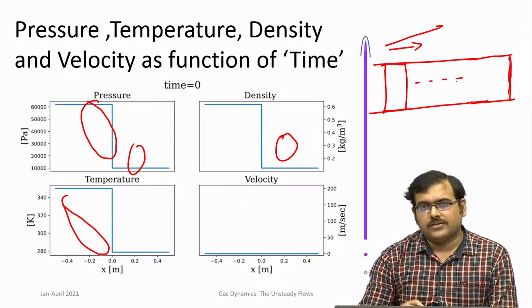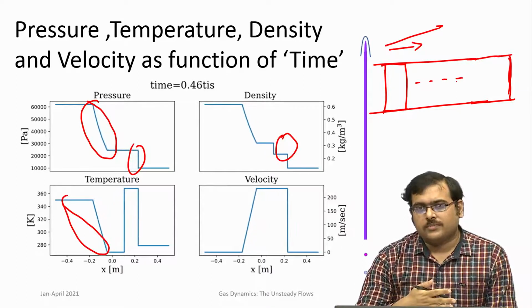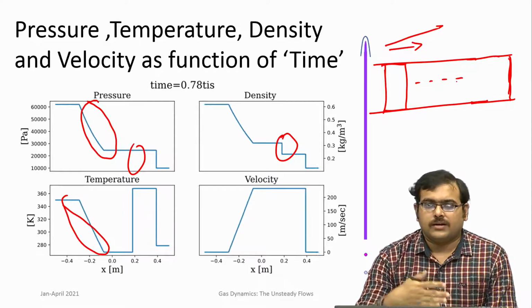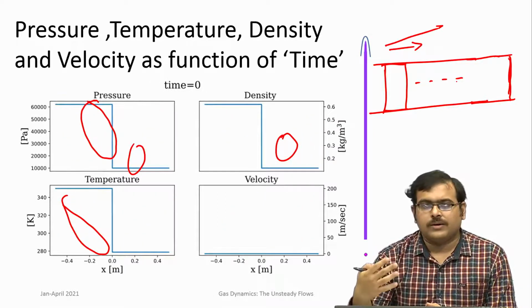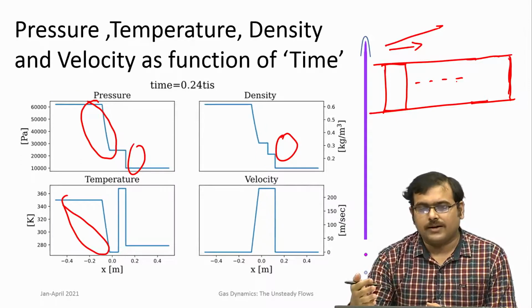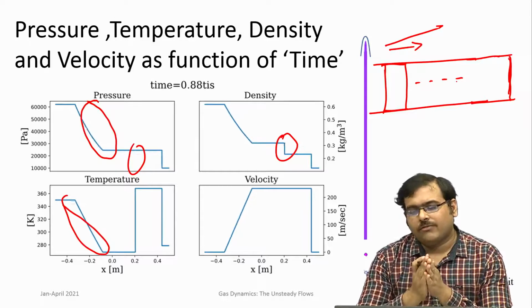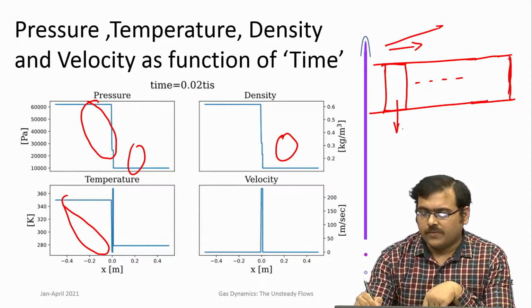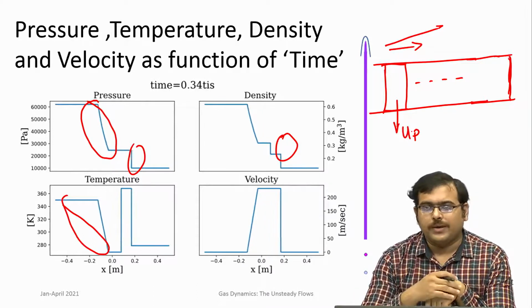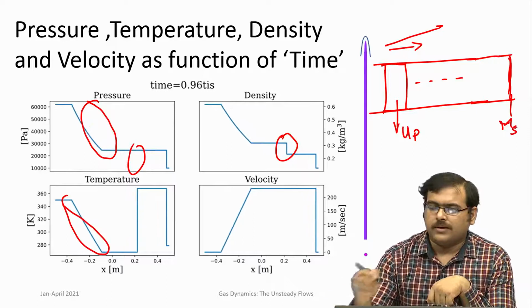Now, these are isentropic compression waves similar to the expansion waves, but you should understand that these compression waves, if you have the forcing for quite a longer time, can actually coalesce together and form shock waves. So, that is where you get the velocity of the piston up to create a certain shock with a certain Mach number.